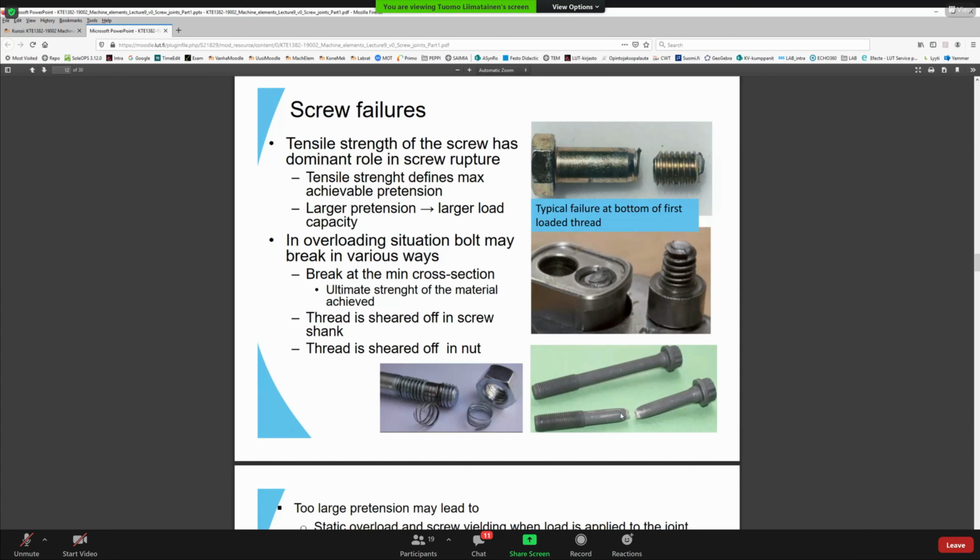How about if you have this kind of bolt and it will snap so that this breakage point would be inside the hole in the cylinder block? How could you take that away? A drill or a reverse, what's that? A screw extractor, which is the reverse thread. Mm-hmm. But yeah, the green one is probably the best if the break is not in the position where it's fixed somewhere, so it's not on the thread.